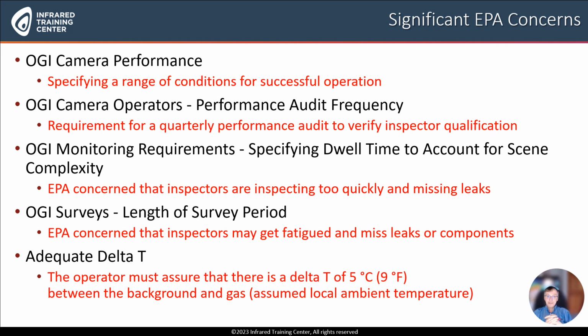They're also very concerned about OGI camera operators. And this comes into the qualification of an operator. So they're going to mandate a performance audit frequency, and that shall be quarterly to verify that the inspectors remain qualified. Also, OGI monitoring requirements, specifying a dwell time to account for scene complexity.